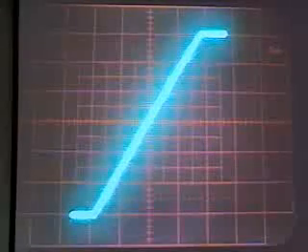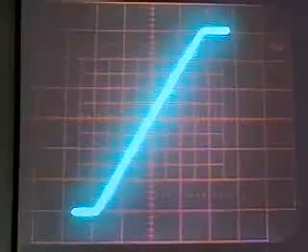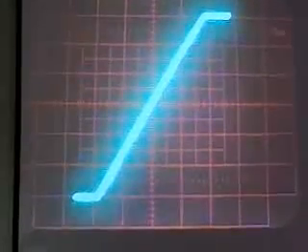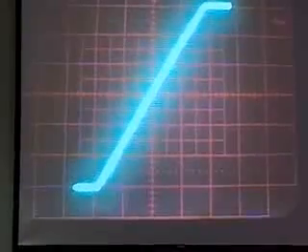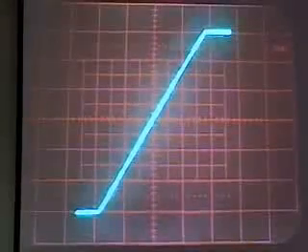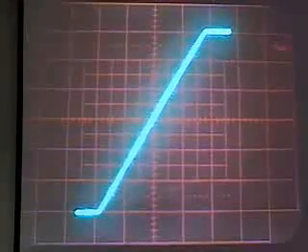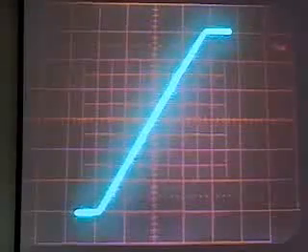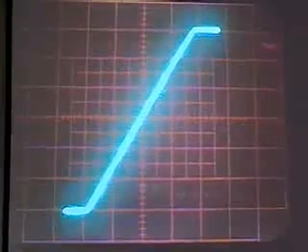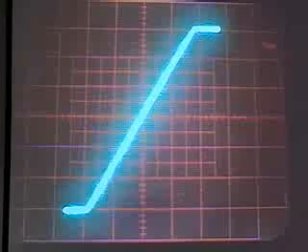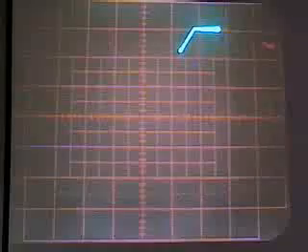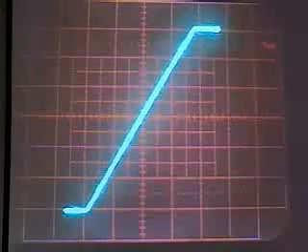So what I'm going to do now is heat the op amp to the wazoo, and this ain't going to change, because it's my external resistors that control it, independent of the value of A, provided A continues to be very large. I'm just articulating the V out, V in curve, and let me start heating the op amp. So notice that it's pretty stable. It doesn't change because it's independent of the amplifier values.